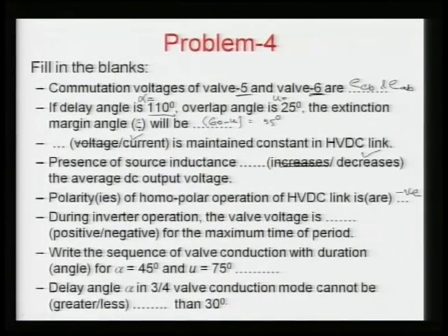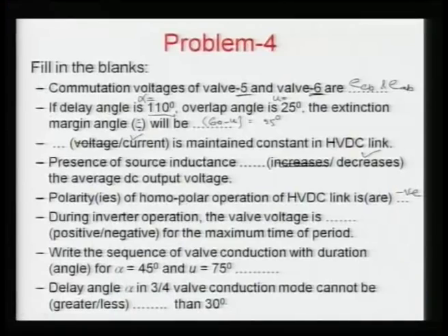Now, during the inverter operation, valve voltage is positive and negative for the maximum period of time. We are going to see in the next problem that during the inverter operation, most of the time the valve voltage is positive, and very little time it is negative. So this statement is wrong and this other one is correct.